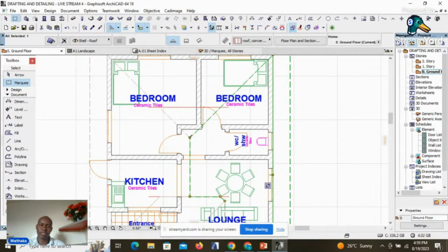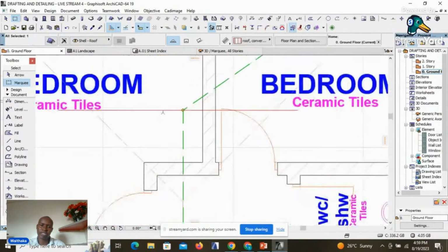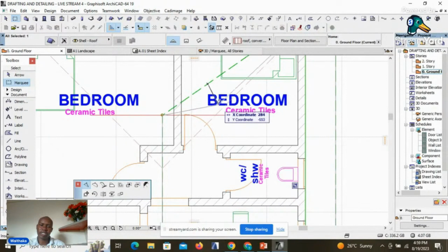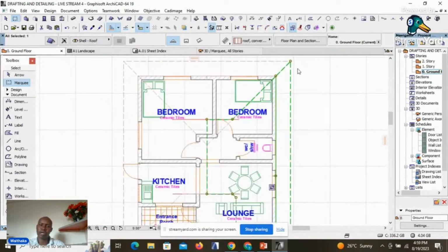We said we select that roof part, click that node using Shift, hold it down, and drag it up to that guideline. Then we pick this edge line, this edge of the roof. But you can see from our dialog box here, it is still under deduct. So we need to change that to insert new node, and then we can insert a node at that interaction. The interaction between the guideline and this roof edge, that's where we will return our edge.